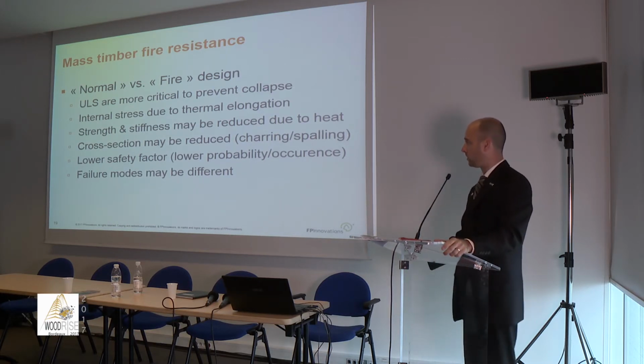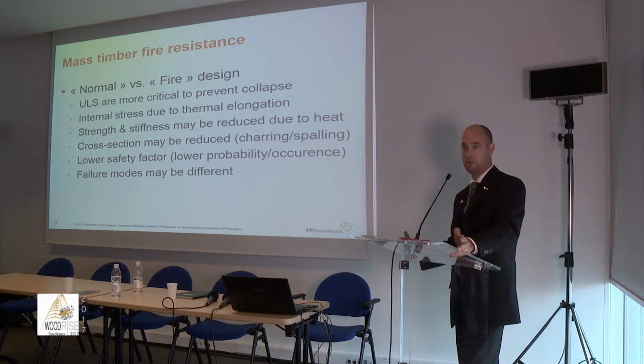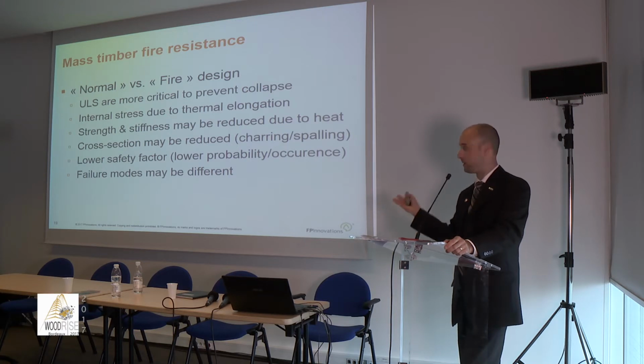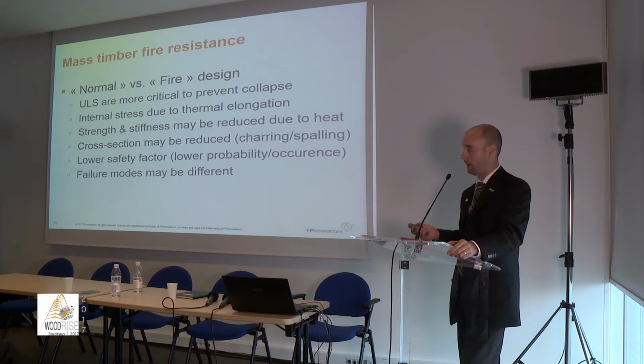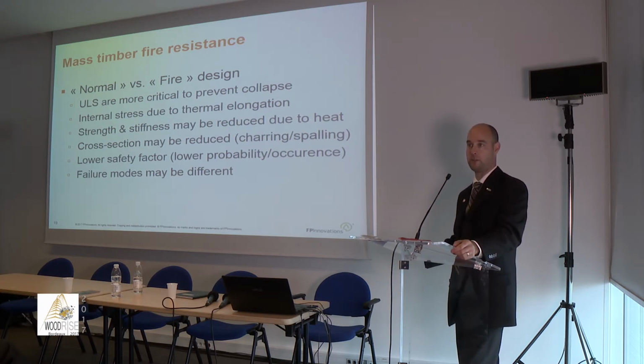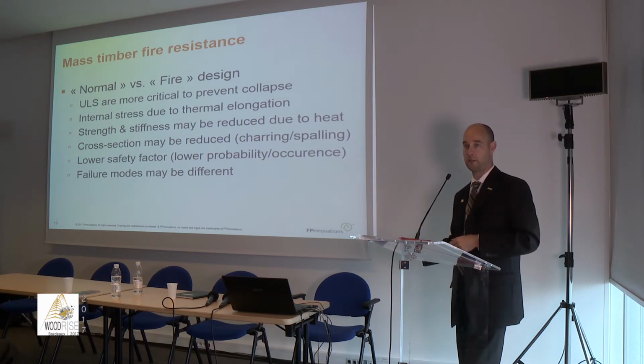Your cross-section changes, so it could be the charring of the timber element, but spalling is also a common phenomenon that we need to account for in concrete. You have different safety factors as well, so the probability of occurrence is not the same in terms of fire load case. And you may also end up with different failure modes. So that also needs to be checked, especially for connections.